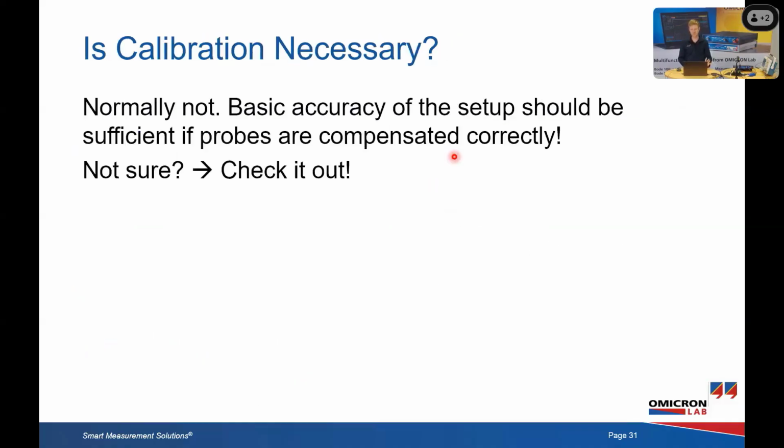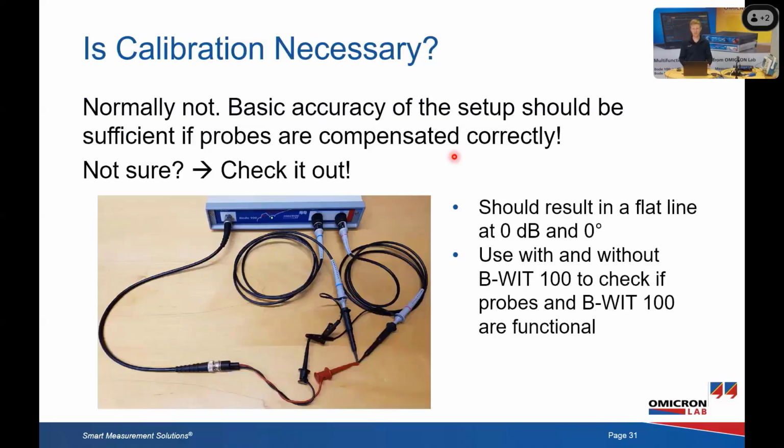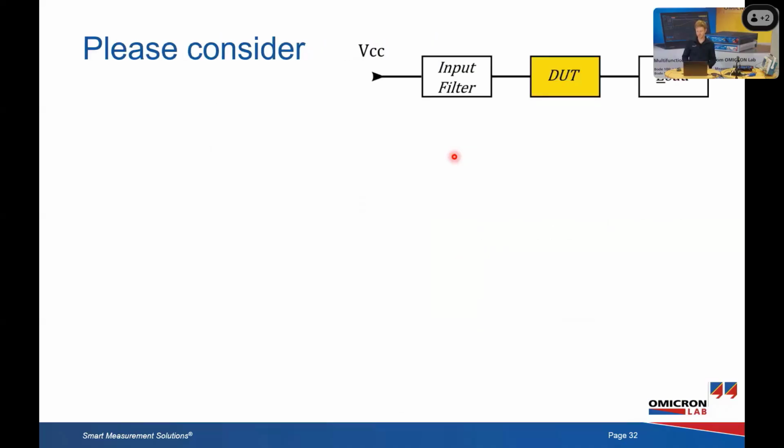Typically, calibration is not necessary, and if you are not sure if your probes are adjusted well and you get a clean result, then just connect both probes to the output of the Bode, and then you should get a clean 0 decibels and 0 degree curve.